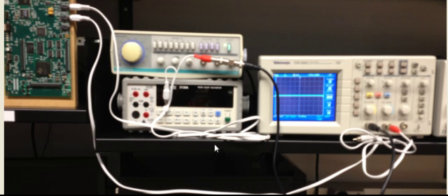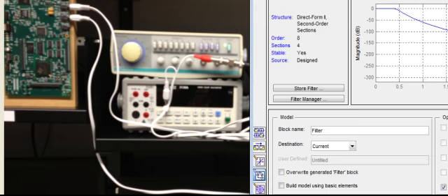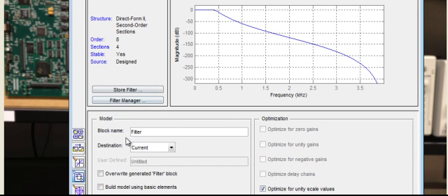For the high pass, you can always switch to a different thing. You can go back to the model and change it so that instead of having a low pass, you can have a high pass or band pass. And don't forget again to do the calculation to change the discrete frequency to the hertz. And again, don't forget that the sampling frequency for both ADC and DAC block are set to 8 kilohertz.